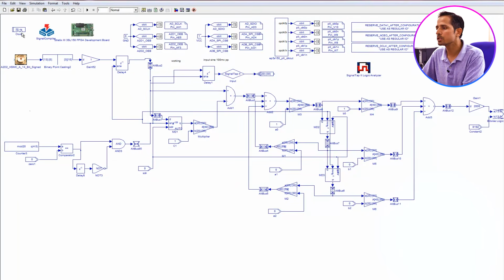We are trying to reduce this clock by counting up to 20, and after 20 it gives one pulse. So we reduce the frequency, so that there is a higher time delay. As the frequency reduces, the time becomes higher and higher, to match the comb filter property.